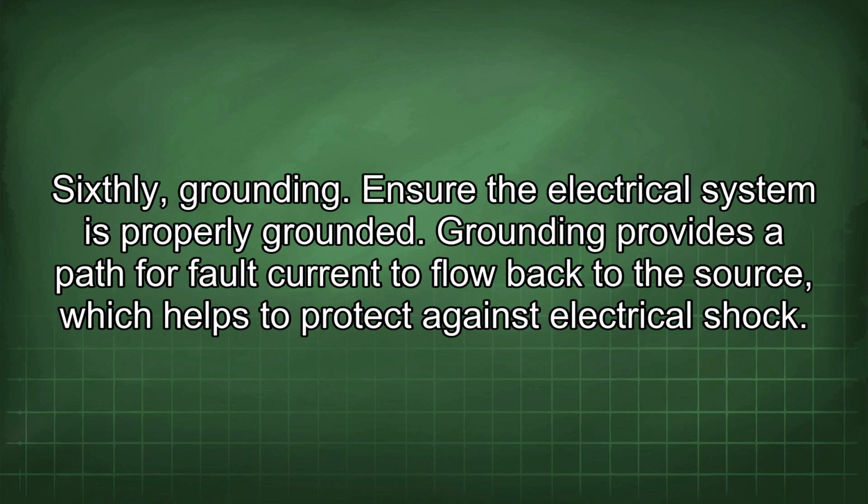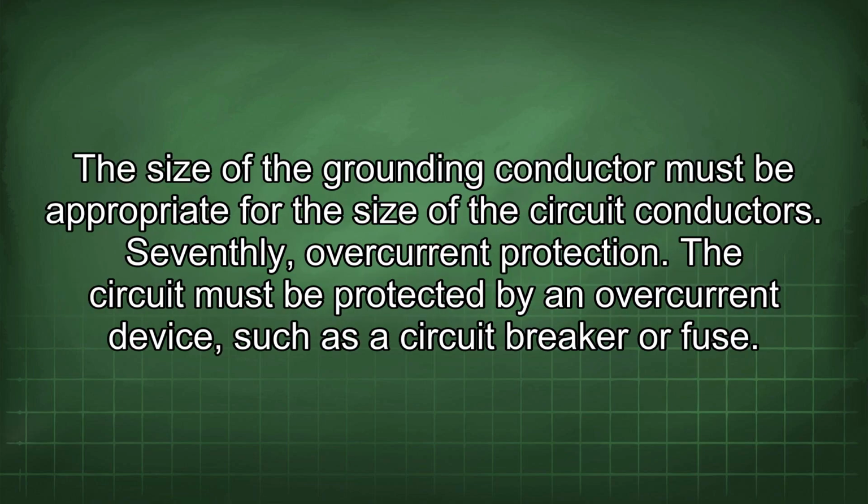Sixthly, grounding. Ensure the electrical system is properly grounded. Grounding provides a path for fault current to flow back to the source, which helps to protect against electrical shock. The size of the grounding conductor must be appropriate for the size of the circuit conductors.